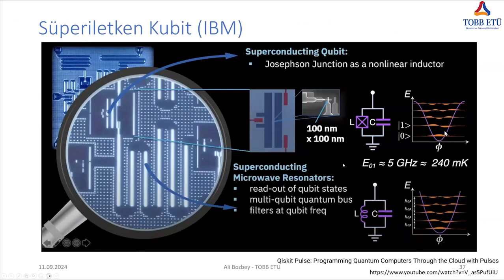At the heart of the transmon qubit, there is this Josephson junction. Here you see a cross, two very thin crossing lines, and in this case they are aluminum. There is aluminum in this line direction, and in between there is aluminum oxide, and then there is another thin line, again aluminum. So you have aluminum, aluminum oxide, and aluminum. So it's a Josephson junction.